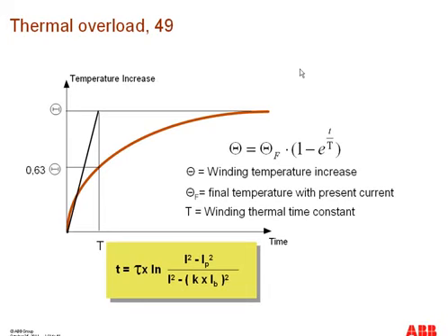Okay, so we were talking about this thermal overload protection. The thermal overload protection estimates the internal heat content of the transformer as well as the generator continuously, and the estimate is made according to this thermal model right here. Normally, two levels are available. One is the warning level, and the other is the trip level.